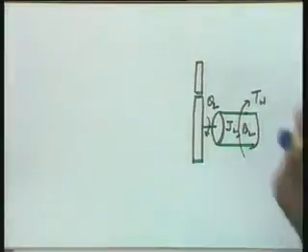Now I have two restrictions, please. You have to give me a suitable system configuration, and then we shall convert that configuration into a block diagram. I want to drive this load. The restriction I have is that I want to use a DC motor and not an AC motor as an actuator. You know that a DC motor is a linear device. The torque speed characteristics of the DC motor are linear as opposed to an AC motor. And the torque handling capability of a DC motor is more than that of an AC motor for an equivalent size. So I want to go for a DC motor as an actuator.